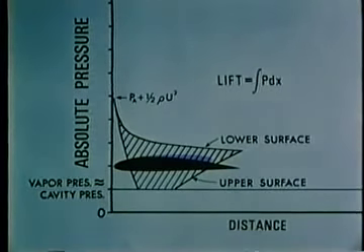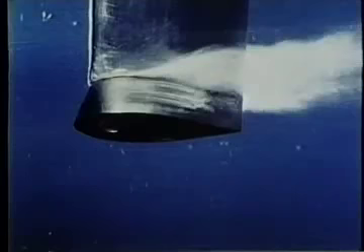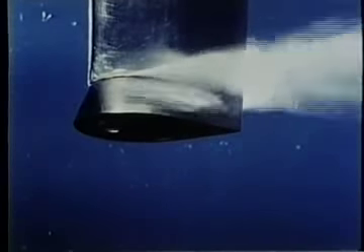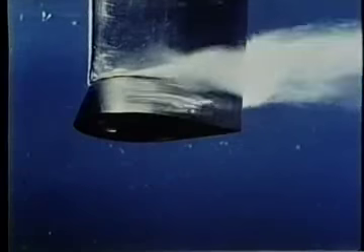Actually, as cavitation develops, the shape of the pressure distribution changes somewhat. The resultant pressure distribution is such as to cause an increase in drag. Thus, hydrofoils, and for the same reasons, many hydraulic machines, which are designed for efficient subcavitating operation, lose efficiency when cavitating. Where cavitation is unavoidable, and conditions are such that supercavitating flow can be assured, it is possible to use supercavitating hydrofoil profiles specifically designed to achieve high lift-drag ratios.